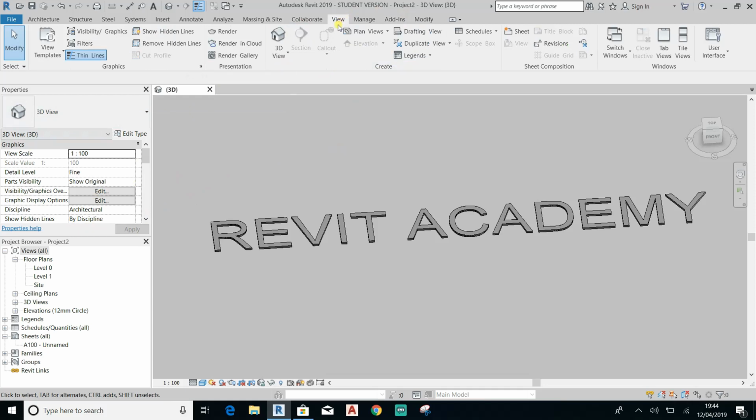So moving on to the View tab. Ceiling plans, 3D views, wall sections, door schedules, legends, you name it. It is all created from here. You can control the sheets and the title blocks as well. So as you can see here, you've got your visibility graphics.